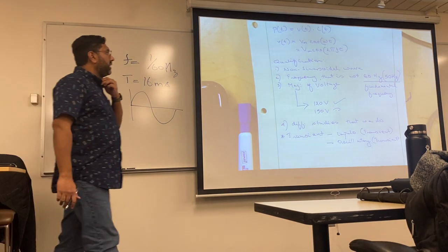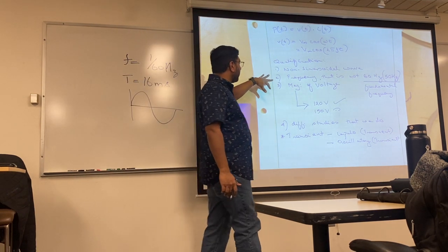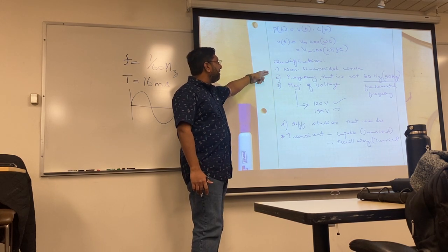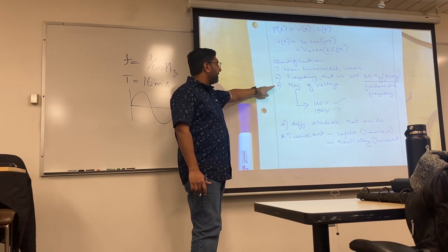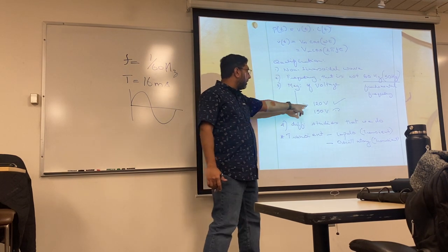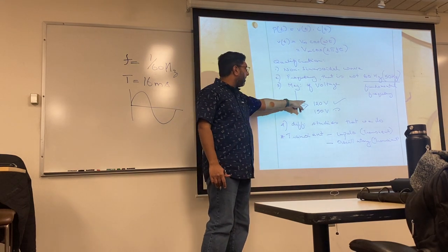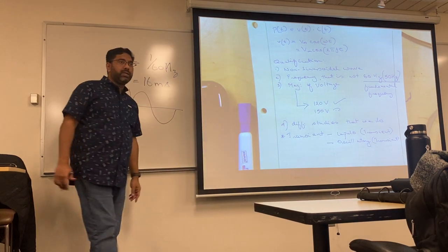Oh, so these are the qualifications for power quality. When we talk about power quality, we are looking at these 3 things. At the minimum, I'm talking about, hey, am I giving a sinusoidal wave? Is my frequency at 60 Hertz? Is my magnitude the agreed voltage? So the problem that you did is 480 volts. Here I'm just talking about the resistance. Is that clear?